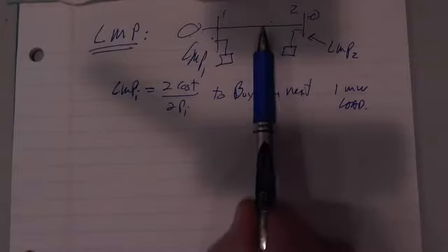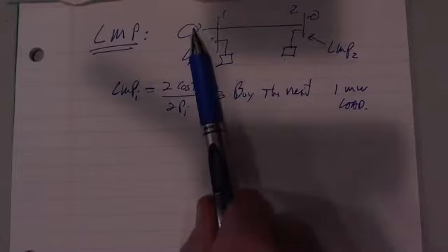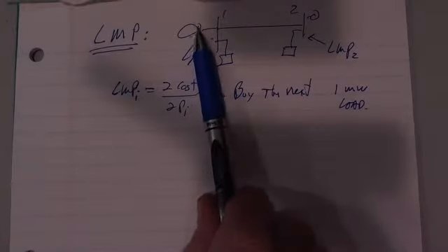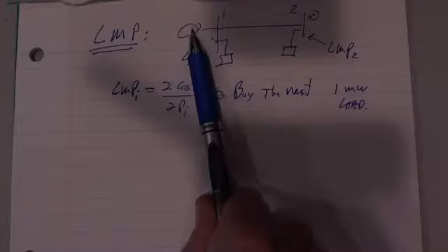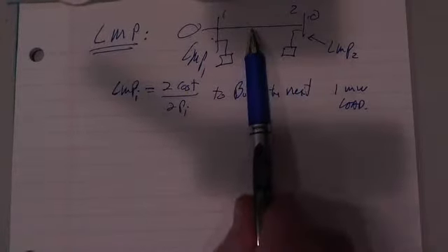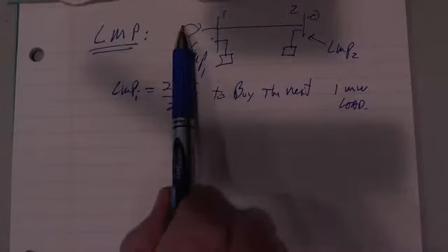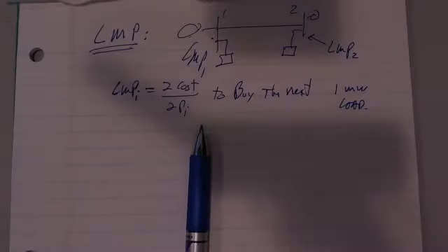And because of constraint, remember when we had no constraint on this line, then it was always equal to the cheapest cost of whatever segment was still available, and both of these had the same LMP. Once we had a constraint, then the next megawatt either comes from this generator or this, and the costs are different. And the LMP is used to allocate costs to the loads.